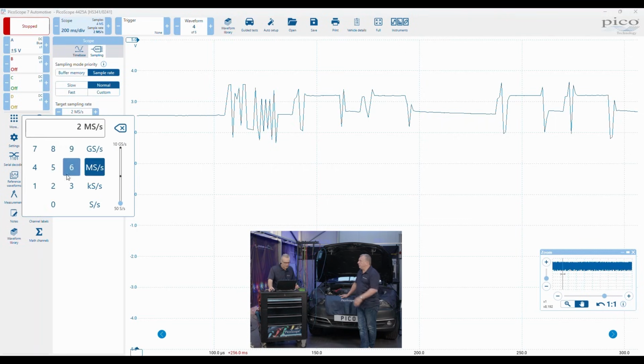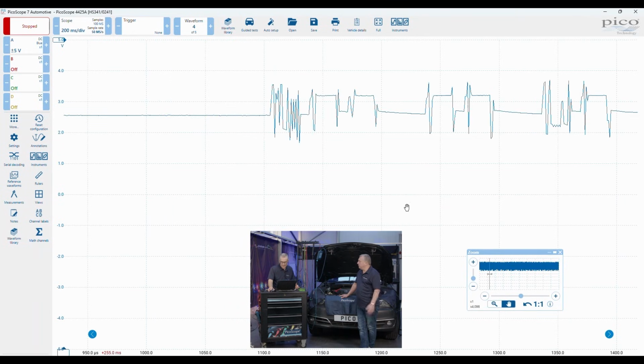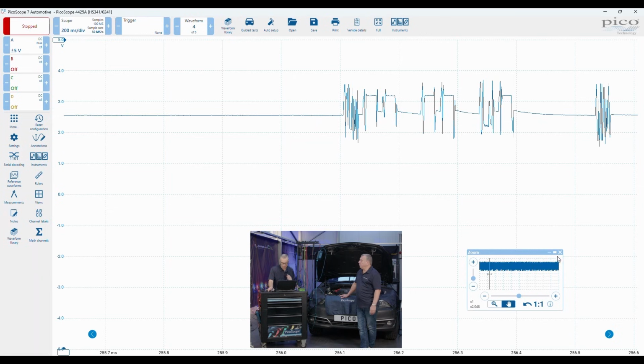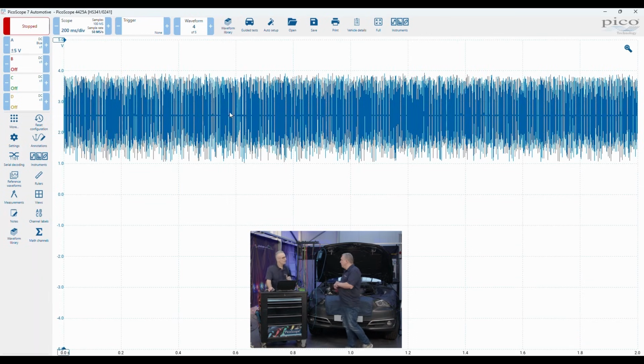But I think it's valuable to show people what would happen if you just approach FlexRay like you would a CAN fault. It's probably worth noting that using the normal ×1 lead is good for speeds up to? That's a great question. For CAN, you're fine there. 1 meg CAN, I think personally, I get anything above 500 kilobit per second. So for your classic CAN, fine. When you get to CAN FD, which is up to 8 meg, then go for a ×10 probe.